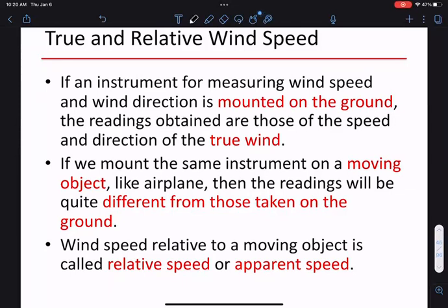So the angle of attack is sometimes hard to measure because we don't always know the true direction the wind is coming in. So next class we'll convert the angle of attack to something called a pitch angle, which is just an easier angle to measure for us. And pitch angle control then becomes the main control mechanism for wind turbine power.